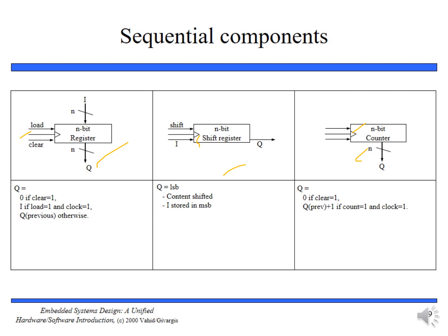There is another common type of flip-flop known as the JK flip-flop, which is the same as the SR flip-flop except that when both J and K are 1, the stored bit toggles. When both S and R were 1 in the previous case, it was not defined, but when J and K are 1, the output will toggle. If it was 1, it will go to 0. If it was 0, it will go to 1.